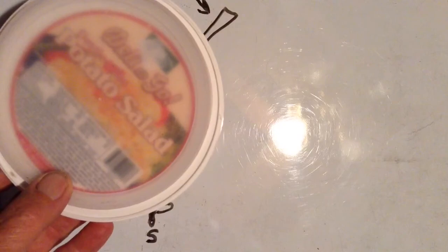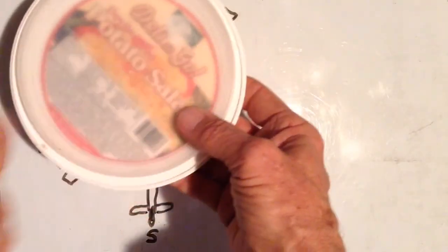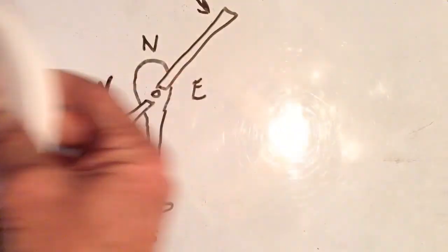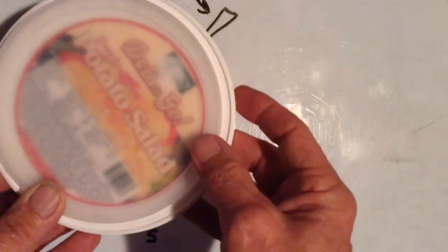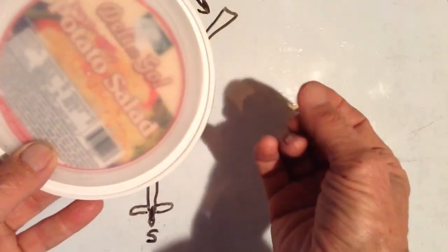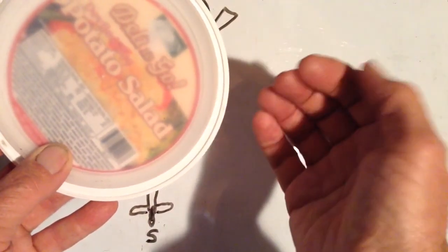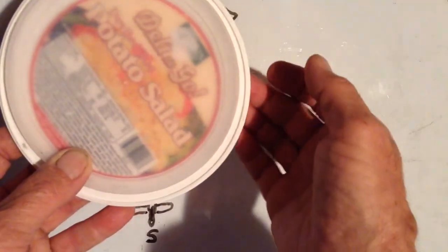So you would think that since the greatest angle of attack is when the rotor is on the east side, the rotor would lift up on the east side and go down on the west side, and the helicopter would move toward the west. But that's not the way it works. With a gyroscope, when you put a force over here, which we're doing by having a greater angle of attack when the rotor is to the east, it has more lift there than when it's to the south, west, or north.